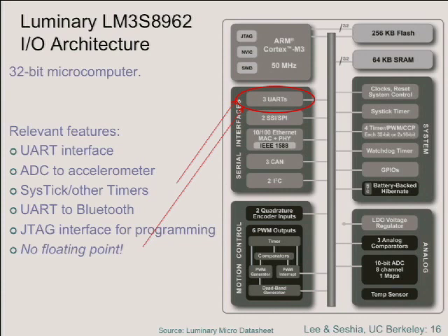A to D converters, we'll use a lot of those in the lab. There are basically two different mechanisms for A to D converters. They can be pretty simple, but one is called polling, where you set up the A to D converter to measure a physical quantity at some rate, and all it does is measure it and stick the value in a register.